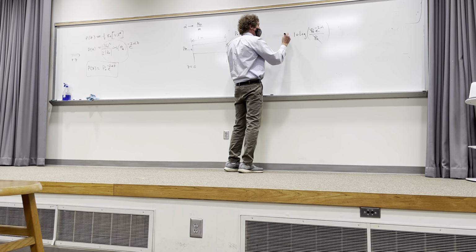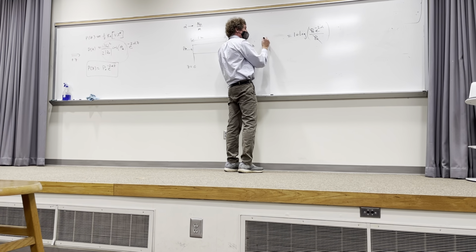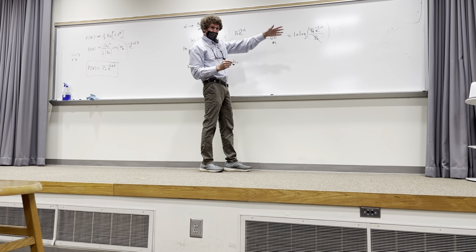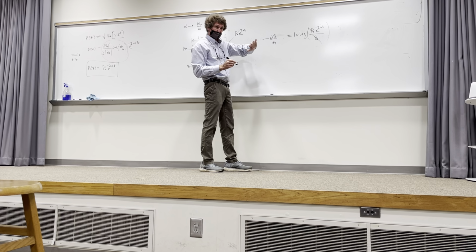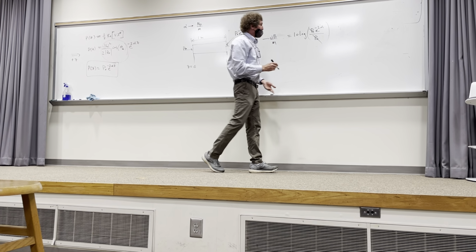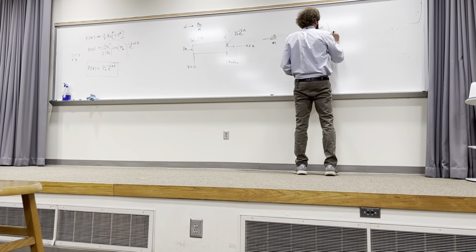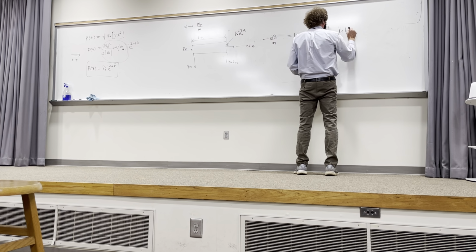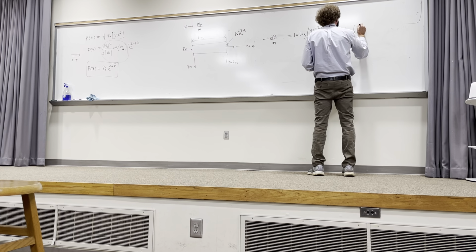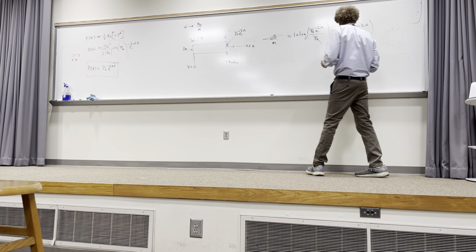Now remember, this is the attenuation, and it would be in dB per meter. I took the ratio of the output power to the input power for a 1 meter section, so it is a difference in dB per meter. When you look here, I have 10 times the base 10 log of e to the minus 2 alpha.